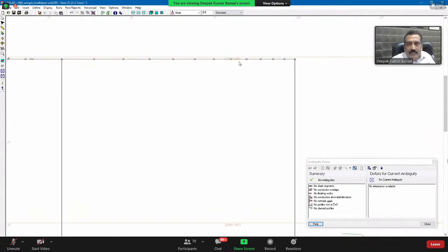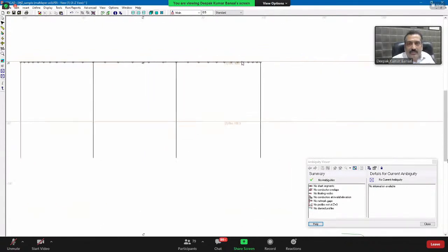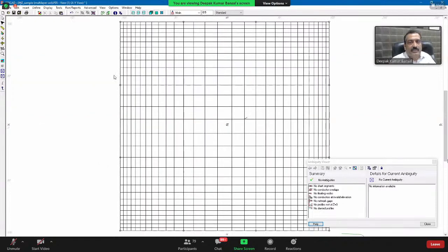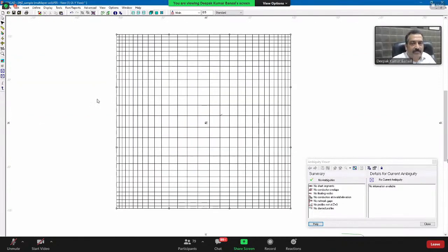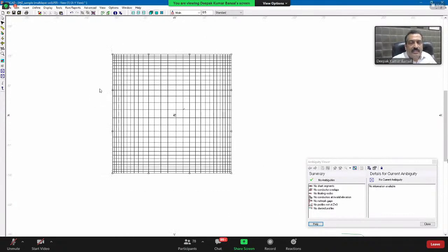And you can see this is the first layer of soil, 4000 ohm meter, this is the second layer of soil, 190 ohm meter. And we have inserted ground rods in such a way that we have deep penetration in the low resistivity soil, so that we can make use of that portion. Otherwise, our grid resistance will be very high.